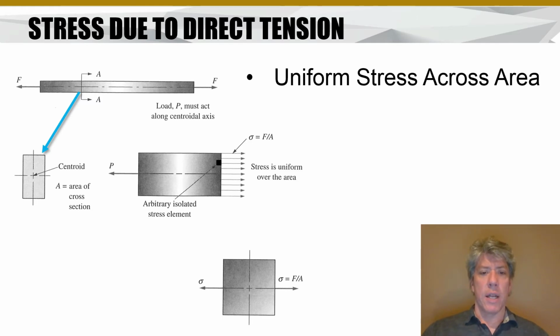If you're thinking, well, I need to balance the load on either side, right and left essentially, but why couldn't I just put a shear on the top of this thing? Well, if you put a shear on the top, now you've got a moment, and it can rotate. To prevent that, you'd have to put an opposite shear on the bottom face and then two more shears on the left and right face. And it turns out that would not work because you could never generate a left and right net load or force or stress with shear stress.